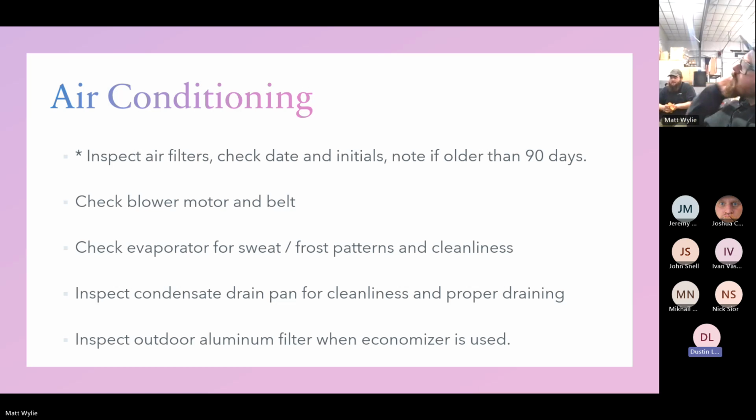And you know, I've dealt with some where I've fought it and I've gone as far as I can go, and now I can't get the belt on because it's too tight. Chances are it's not the right size belt for that unit if I'm still not achieving the proper amp draw on my motor. So just because there's a belt on it and just because it's running, the amount of air you're pulling through your evap coil is really critical on air conditioning.